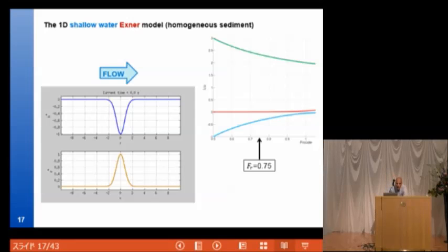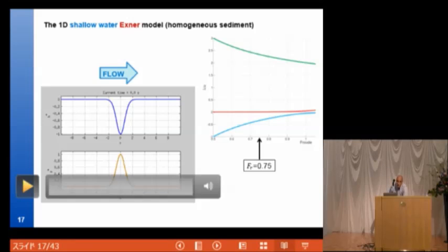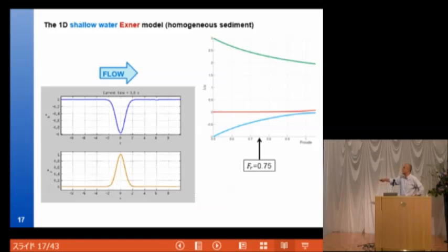Okay, let me show this once again. So you can see here this wave and nothing happens here. Then you can see this other wave, which is this one, and nothing happens on the bottom. So it's too fast to trigger a variation in the bed, actually. And the bed is traveling downstream, and while it's traveling downstream, it also changes the water depth.